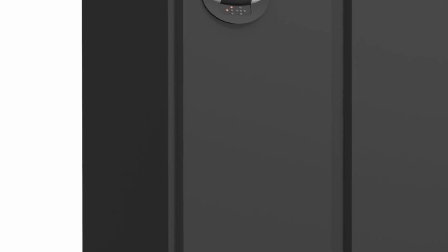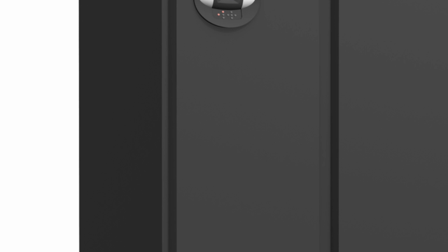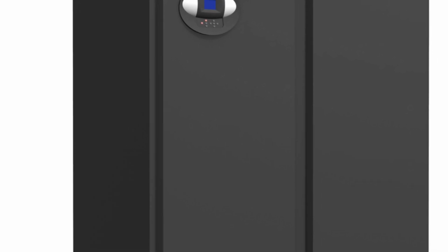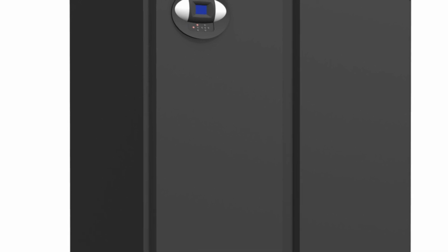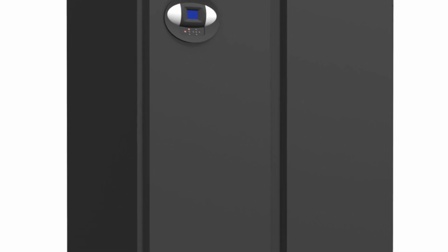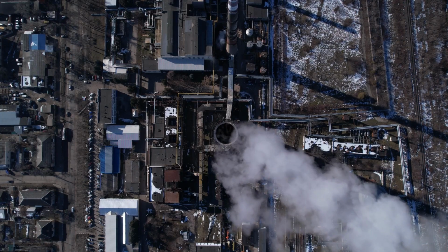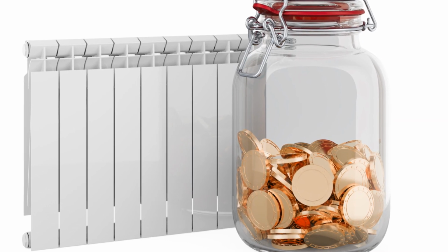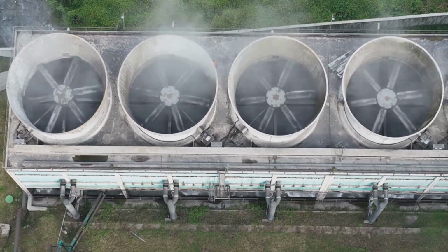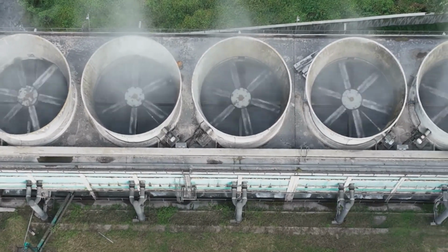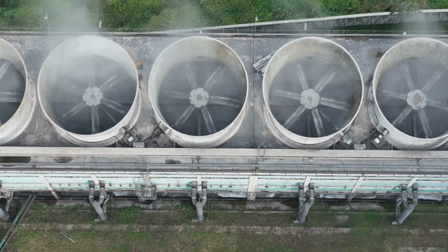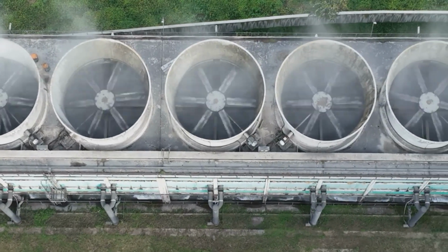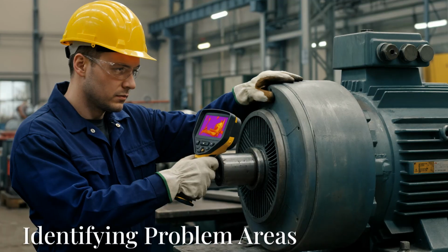critical. With advancements in technology, industries are adopting smarter heat dissipation solutions. One such advancement is AI-driven cooling, systems that adjust fan speeds and coolant flow based on real-time data. Another advancement is waste heat recovery, repurposing excess heat for other processes to improve energy efficiency. Excess heat buildup is one of the biggest challenges in equipment reliability. Whether through passive cooling, active systems, or smart heat management strategies, efficient heat dissipation is key to performance, safety, and longevity.